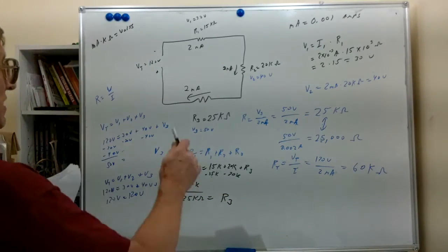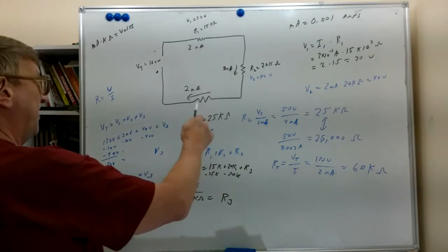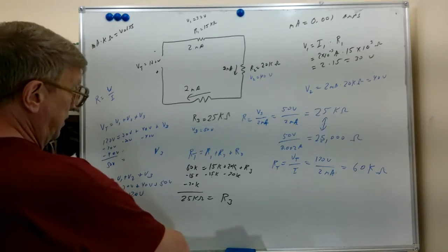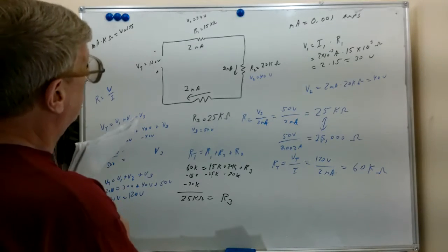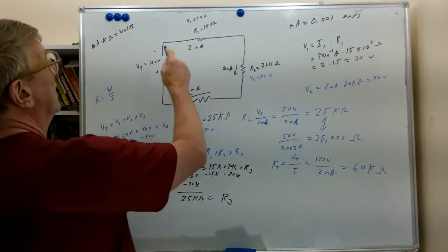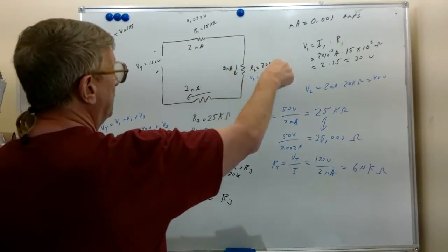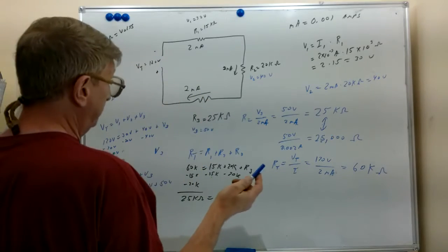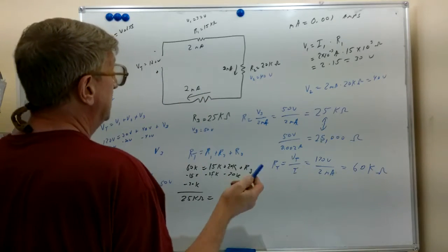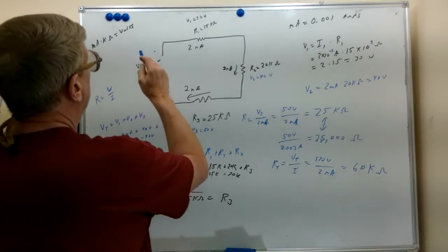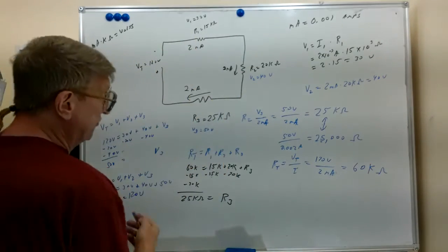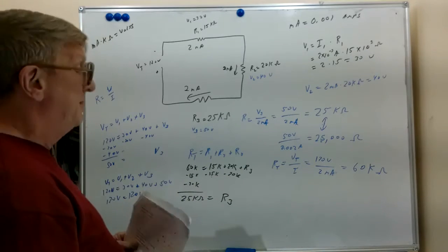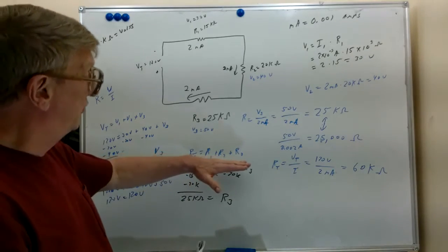So we calculated current, we calculated voltage drops, we found the voltage drop across R3 and used that to calculate the resistance. The other thing we did is we took the given voltages, the given current, calculated voltage drops, and we used the voltage and current to find out what the total resistance would be, which we did here, and found a way to get R3 by solving the series resistance formula.